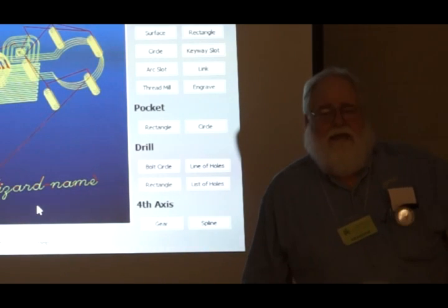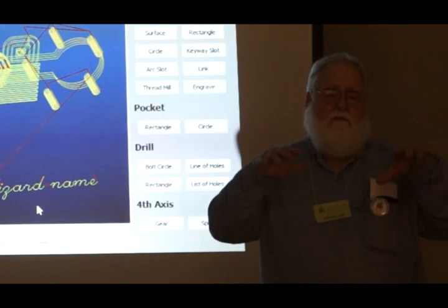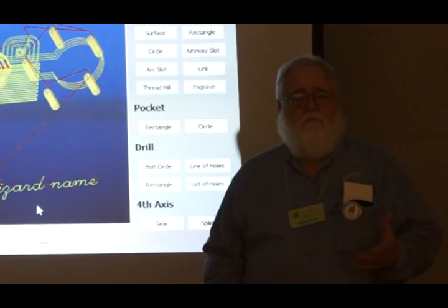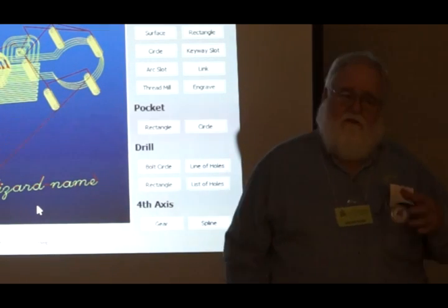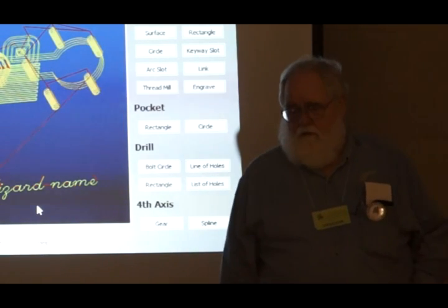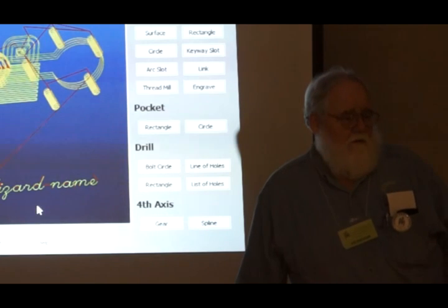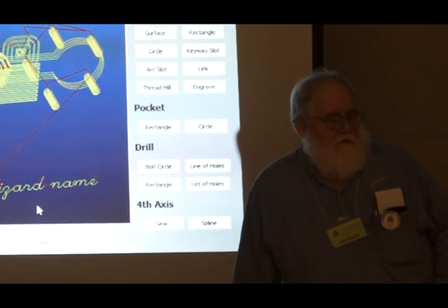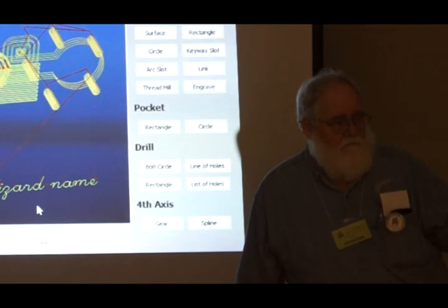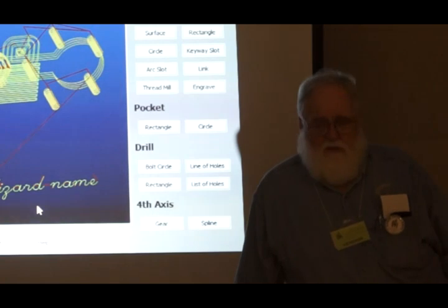But again, my limit is wizards are meant for common, low-level, simple geometry. We're not going to turn this into SolidWorks, and we're not out to knock SheetCAM out of business. If you want to do multi-line, do two operations. Do one engrave, then do the next one spaced down to the right point. So yes, you have to do that. You can't put spaces in the lines.